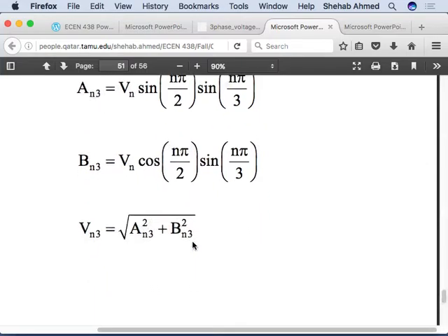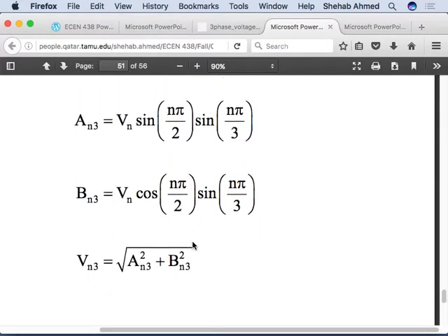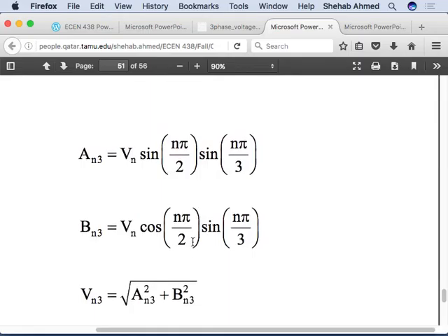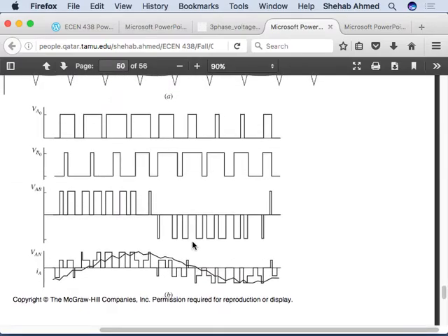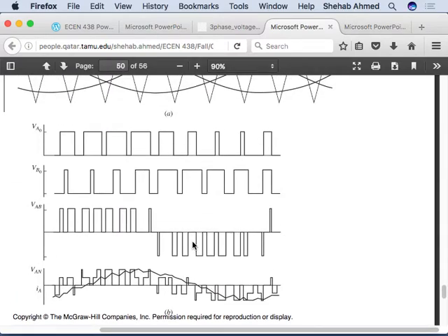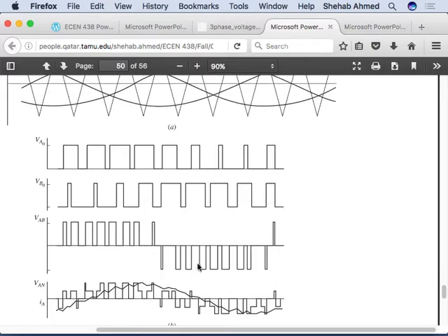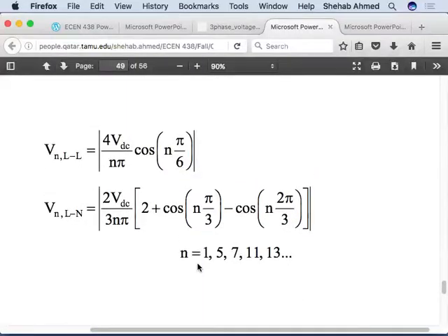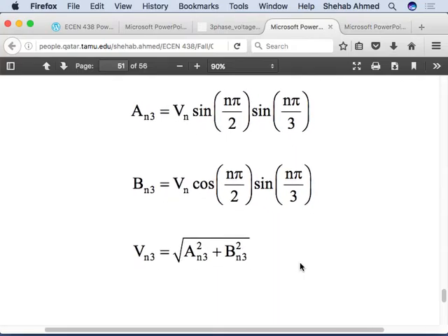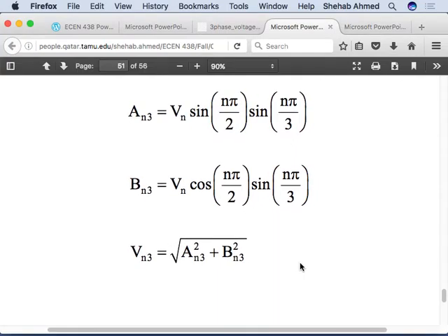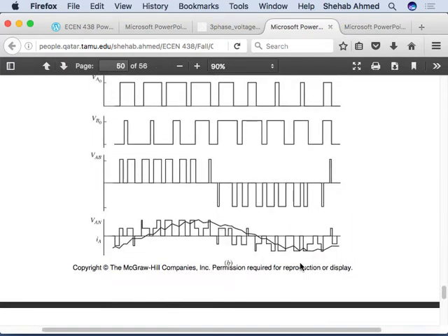I mean, they're the same, right? The idea is the same. But what's very different here, actually? Why is it N3? Means 3-phase? Yeah, it means three-phase, but also this is like unipolar PWM. So it's not like the previous case. The previous case, they gave you 1, 5, 7, 11, and so on. How about here? Do they need to give you 1, 5, and so on? No, they don't, because the first harmonic will be like the unipolar case at twice the switching frequency. So I don't need to worry about it. You just need to worry about the value of your fundamental in this case.